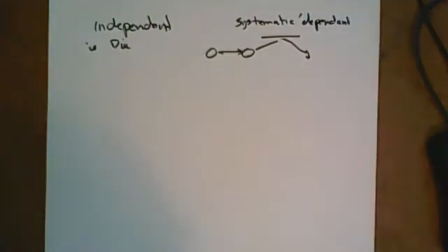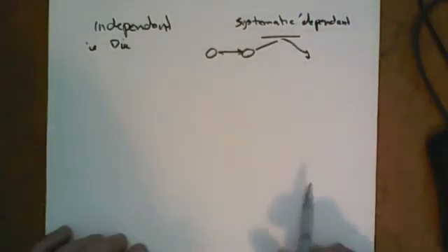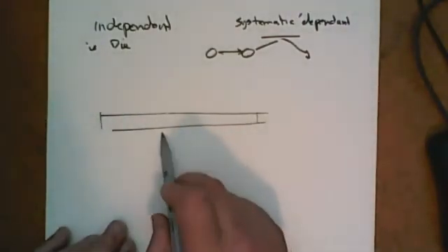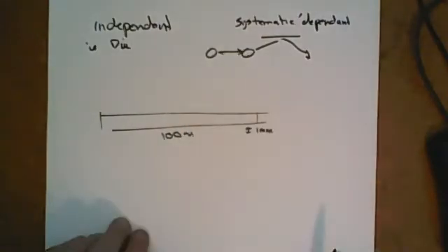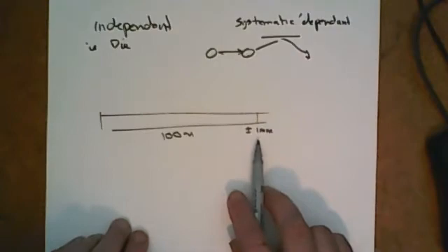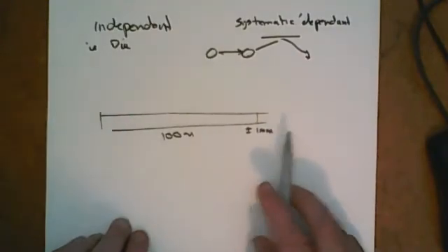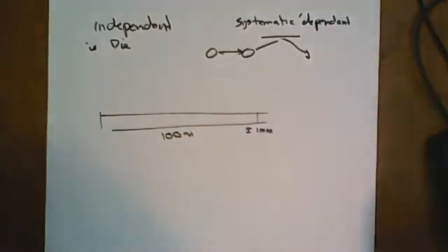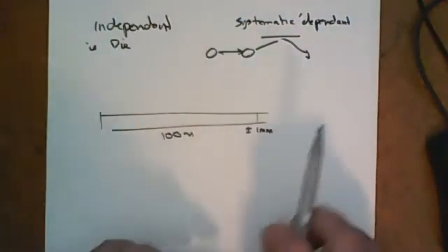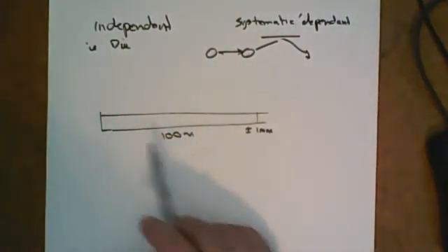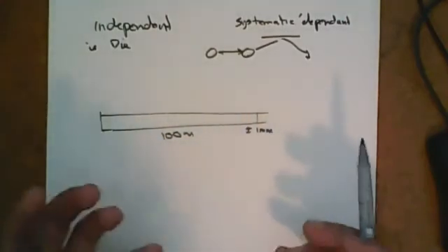And uncertainties. It does get to the ridiculous point now where you get architects say, make a wall 100 meters. Hopefully you can see what the problem with defining a wall is. 100 meters long plus or minus 1 millimeter. And it's quite simple. If this warms up, the wall's going to expand. If it gets cold, it shrinks. But you still get people designing stuff like this.